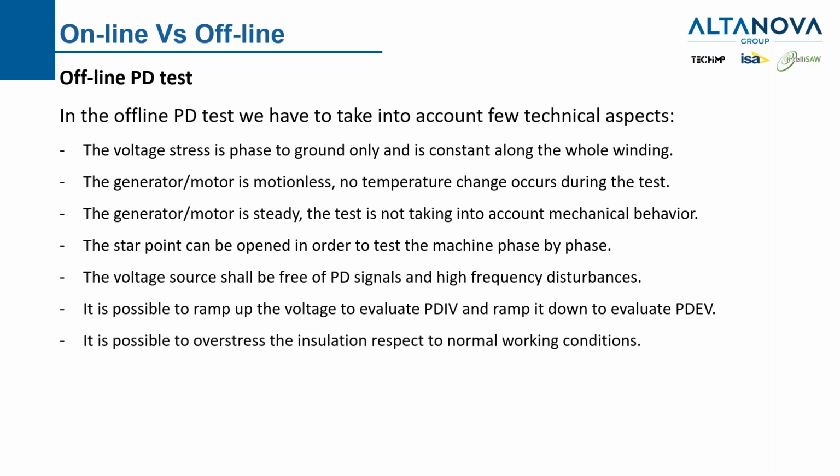Is it also possible to overstress the insulation? We don't have any limit to the voltage we apply. We can go over the rated voltage of the insulation and see what the behavior of the electrical insulation system is.